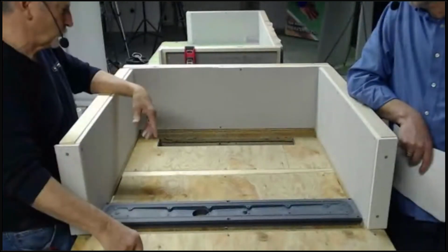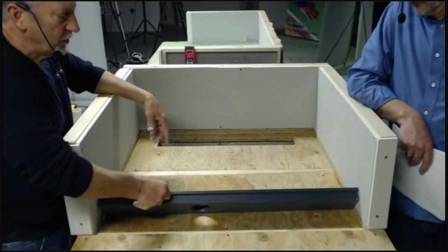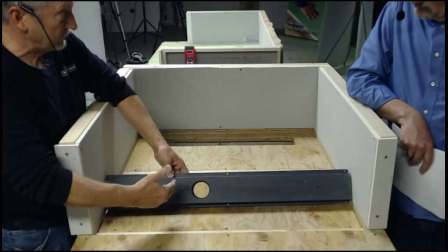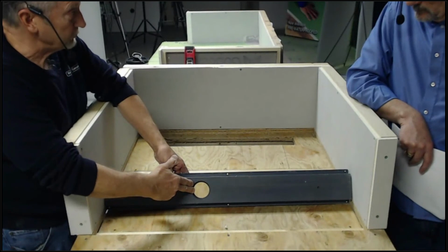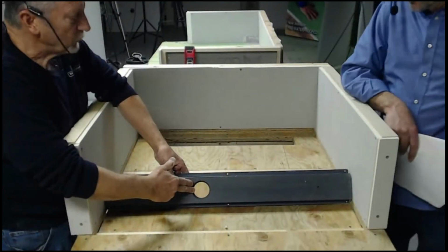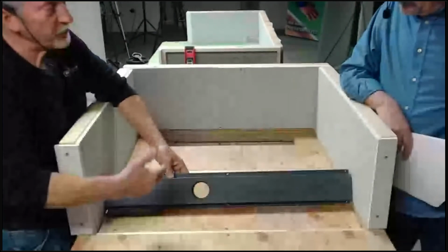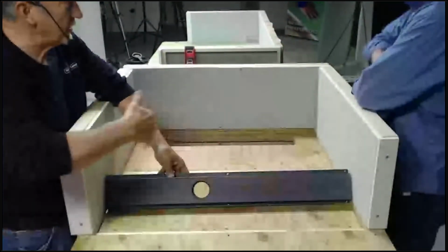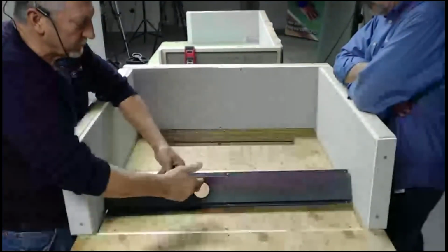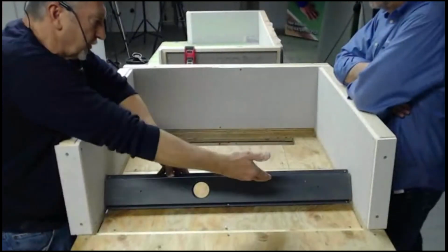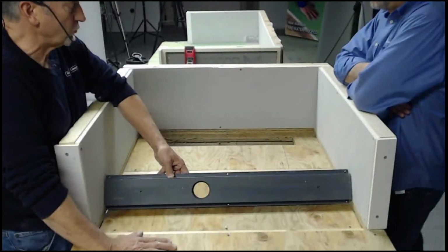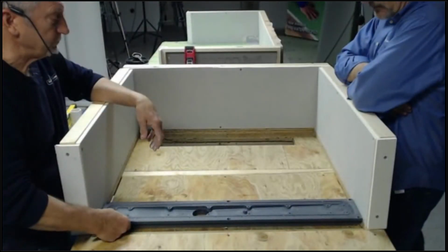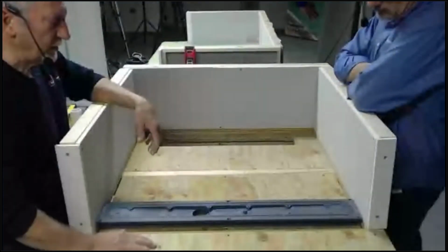I'll determine where my plumbing is, tie in my plumbing. Now, talking about plumbing, as you can see with our Freestyle drain, this particular one is an offset where the drain pipe is standard 2-inch pipe. We also have them in center. But if you have a center drain and the floor joist is right in the middle of that center, now you're in trouble. With the offset, you'll be in the next cavity, or turn around and go to the next cavity over, whichever works best for you. It basically moves you over about 3 inches. So I'll get my drain in place, screw it down.